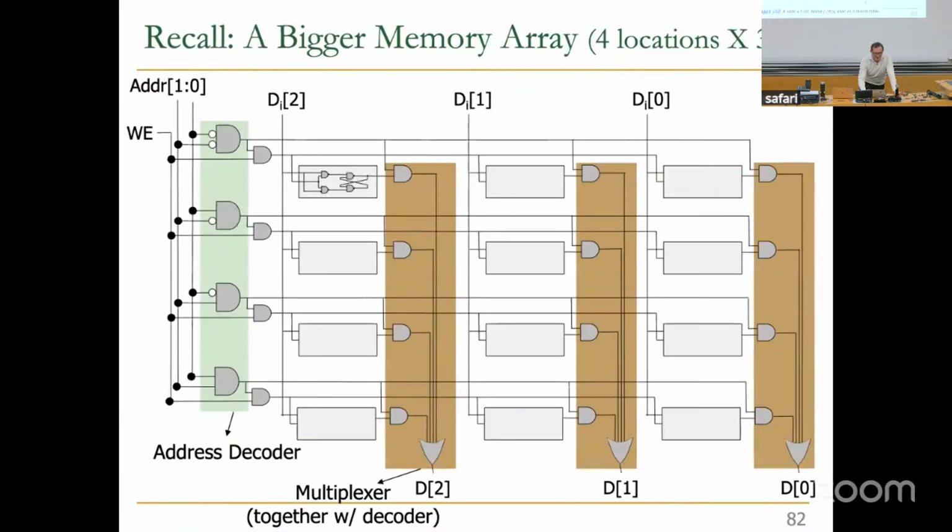Remember, A and B, if you want to implement it using purely combinational logic, is 1 gate. It's an AND gate. If you want to implement it using a lookup table, you need all of the circuitry, right? That's why FPGAs are expensive in terms of hardware. To do the same function as hardwired circuitry, they need to use a lot of gates. But the advantage is they're quite programmable.